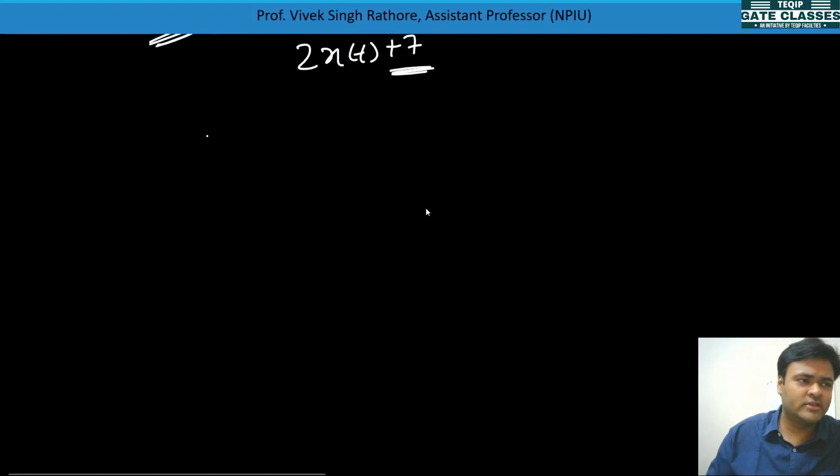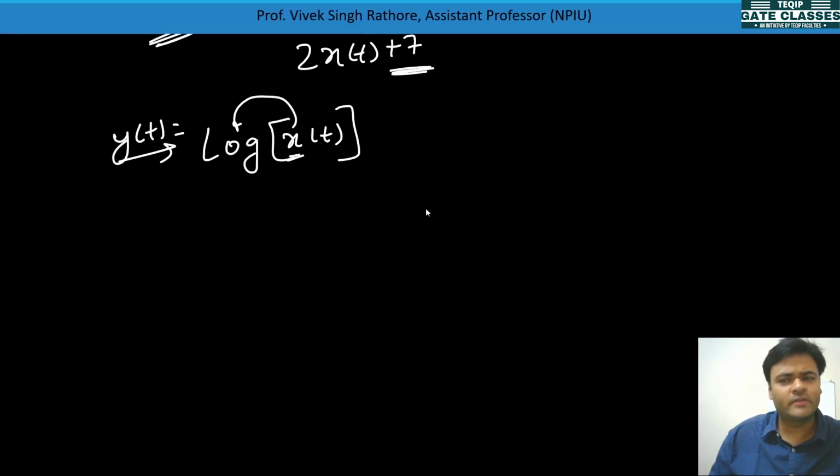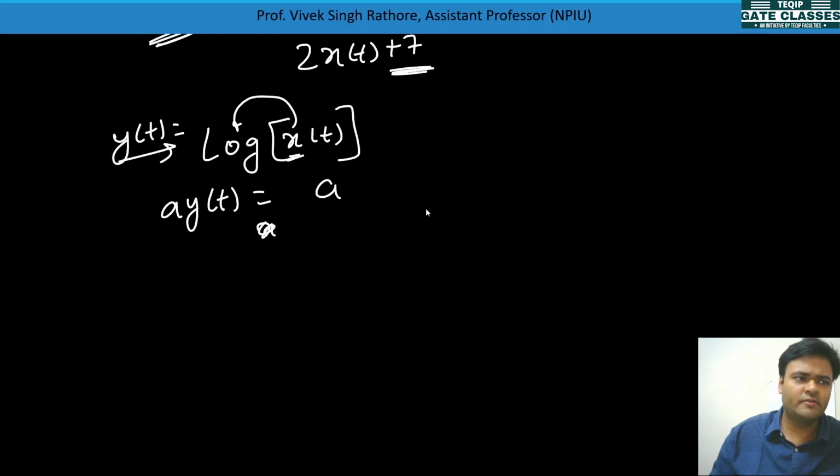Now see, if I tell you log of x of t, and I ask you is the signal linear or non-linear, you will just see something is there for xt also, so it should be non-linear, but we'll check also. See, we'll take a into yt also once, so a into log of xt is there.